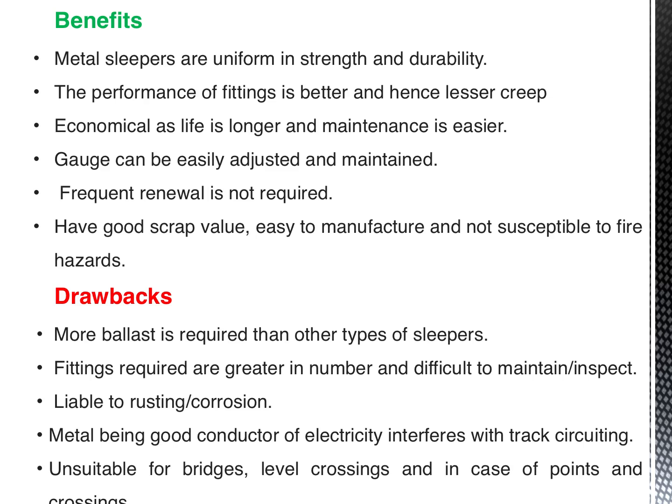Okay, but the drawback here is that for metal sleepers more ballast is required compared to the other types of sleepers. Also, the fittings required are greater in number, and it is difficult to maintain and inspect. And metal sleepers are liable to corrosion, but if you use cast iron, it is less susceptible to corrosion.